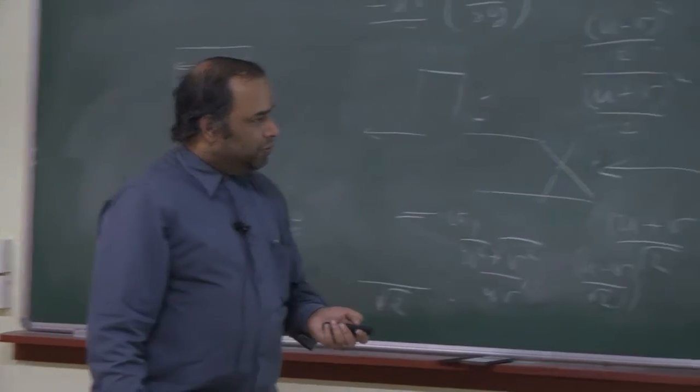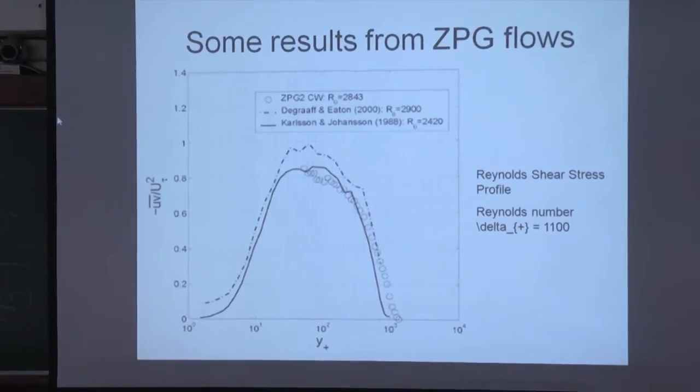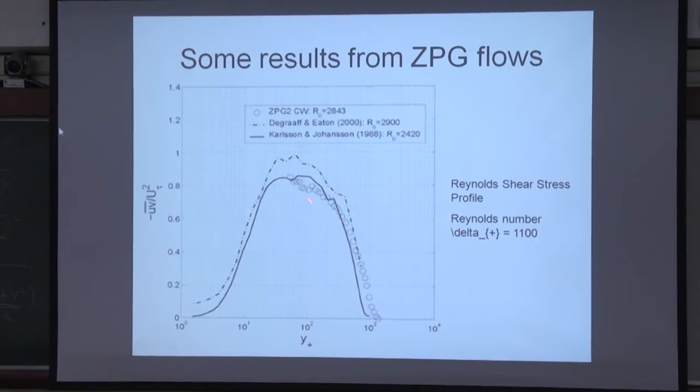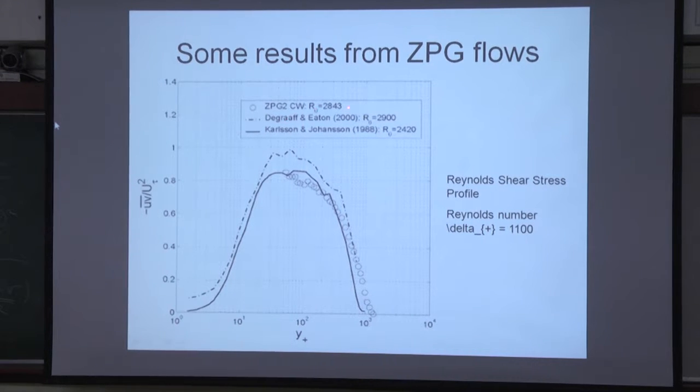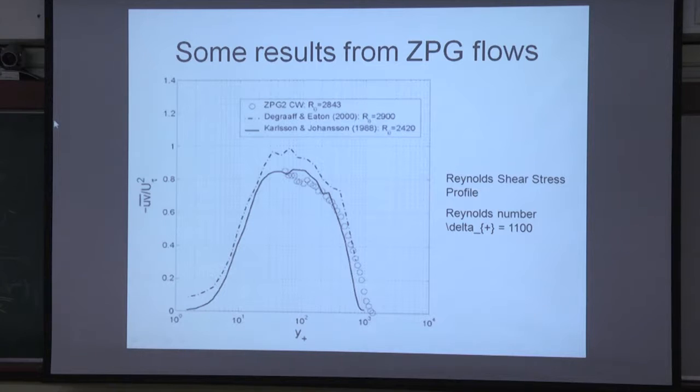Okay, so now this is UV, mainly from the crosswire. You can again see the comparison of the crosswire with your LDV. You see that difference is there because the Reynolds number changes, but look at how it stops here. You don't quite capture the region, right? That's mainly because you can only go that close to the wall with hot wire. You cannot get closer than that.